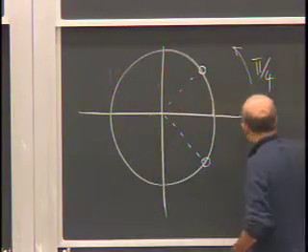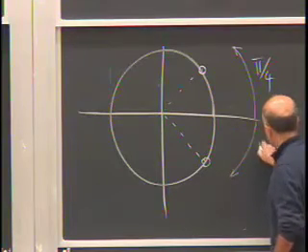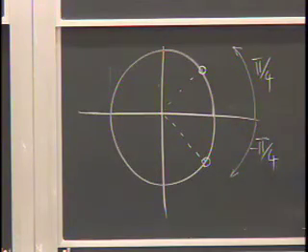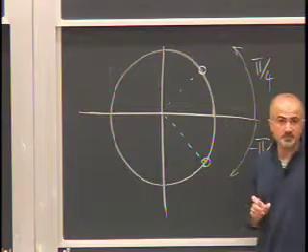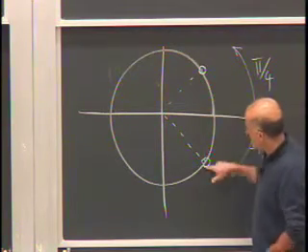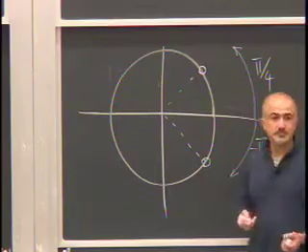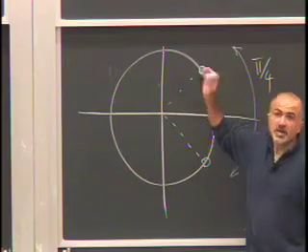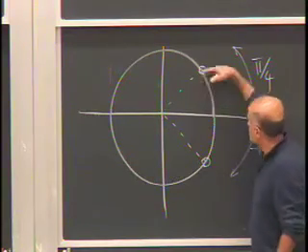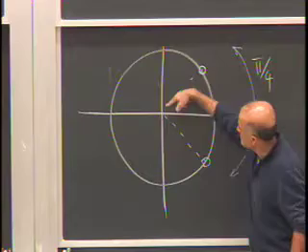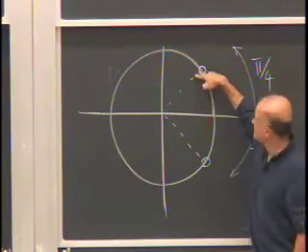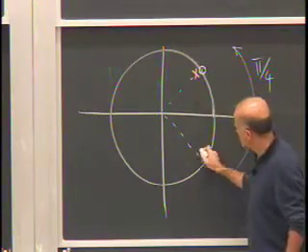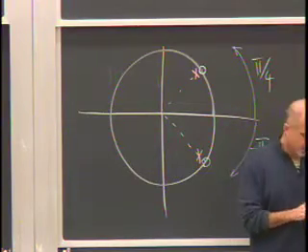Last time we said if we want real valued filters, we want everything to occur as complex conjugate pairs. That's how we get the coefficients of the difference equation to be real. And where do I put the X's, people? Next to them in what way? What angle? Pi over 4. So if I want to stay on the same angle and right next to this guy, I put it right there and right there. Okay?